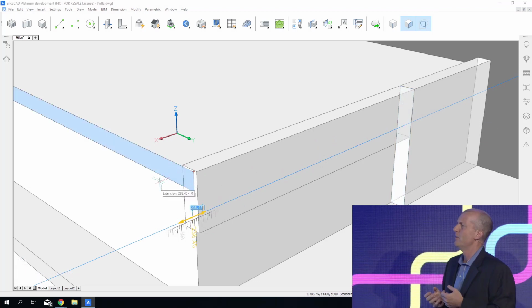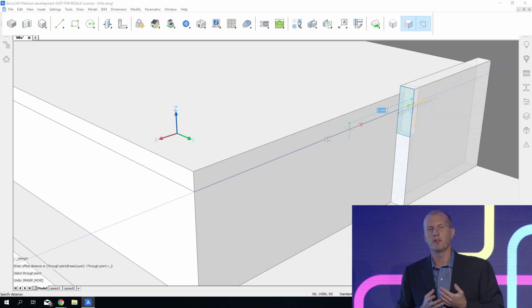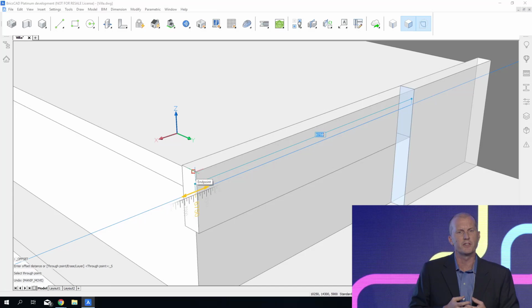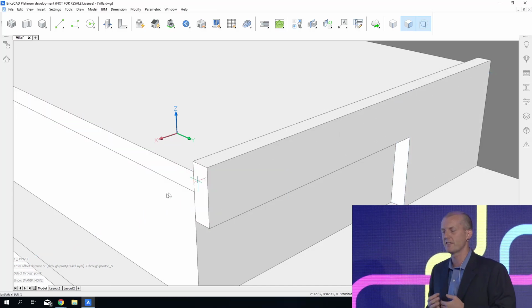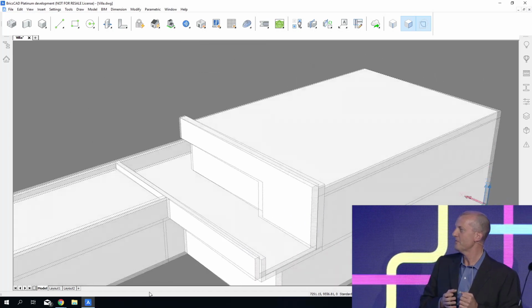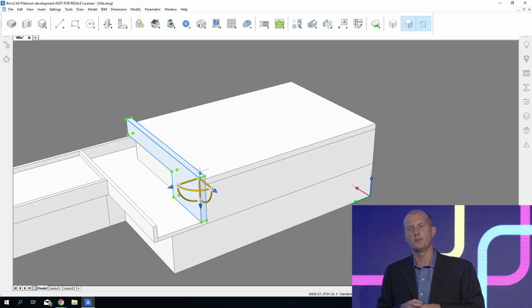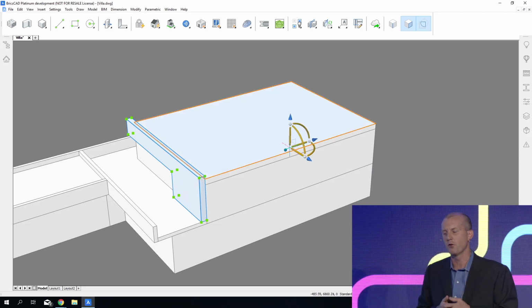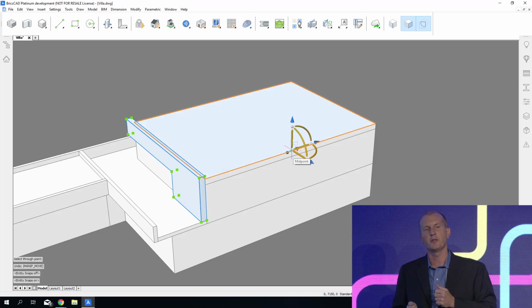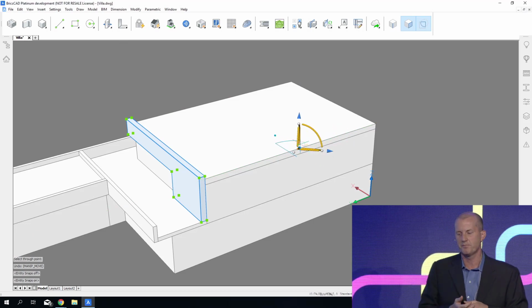And maybe with that, we're starting to see something that might be interesting to carry to the other side of the building. So we could select it, and again, Jacob's showing the ruler. So we could select that, and then we can use a tool called the manipulator, which you've seen before, that will allow us to quickly make a mirrored copy and include that copy of that solid on the other side.